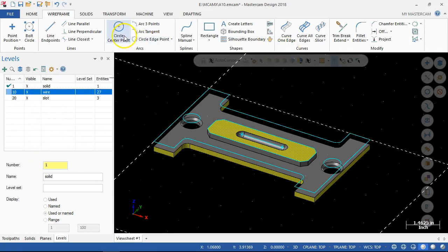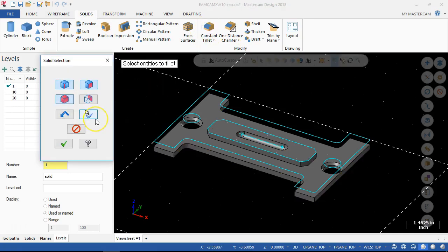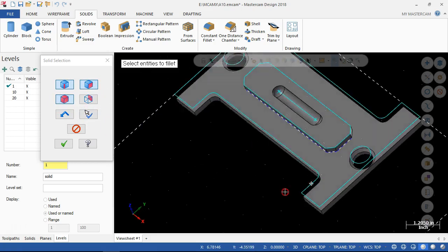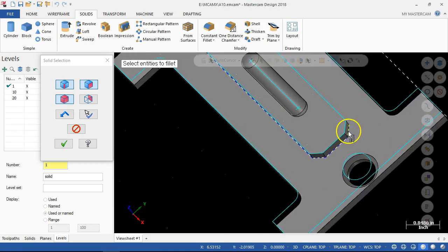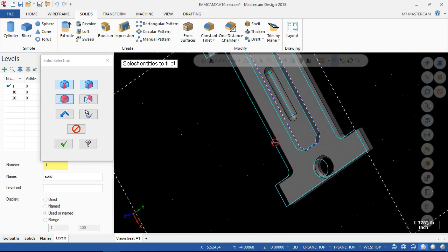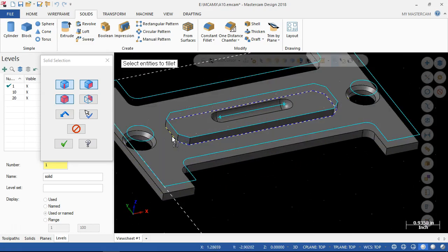So I said one more for the fillets then is that we're going to do a constant fillet, and I'm picking four edges. So there's no find all of the connecting. So the downside here is that I'm going to have to select each one of those edges or each one of the faces to get that fillet geometry in place.